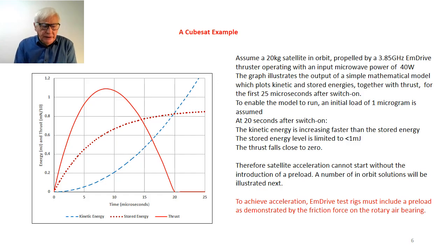And we saw that in the first slide, where we discussed the demonstrator engine being rotated on an air bearing, a rotary air bearing, and the rotary air bearing itself had a frictional torque component which acted as a preload on the thruster and enabled us to watch the demonstrator engine start to accelerate on its rotary test rig.